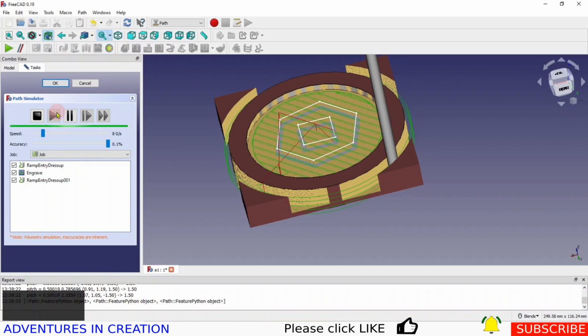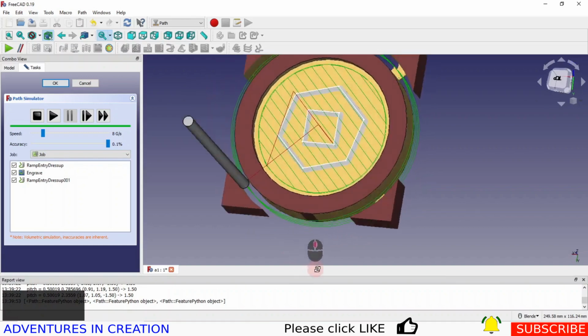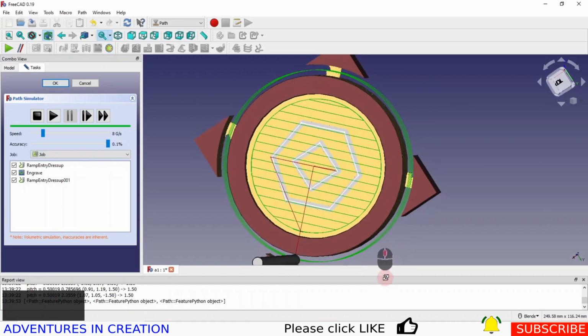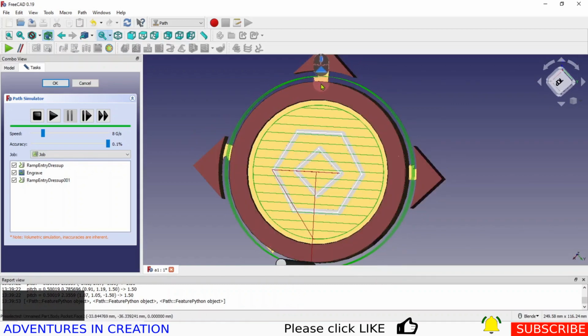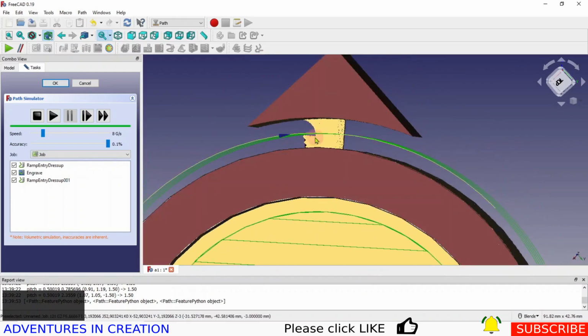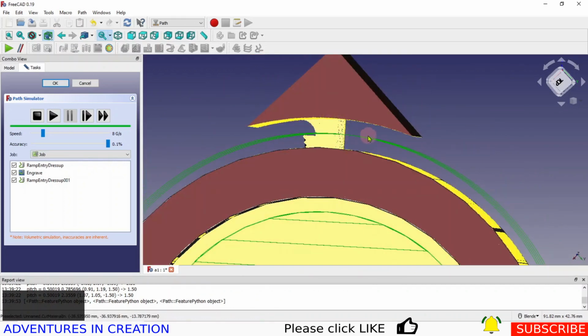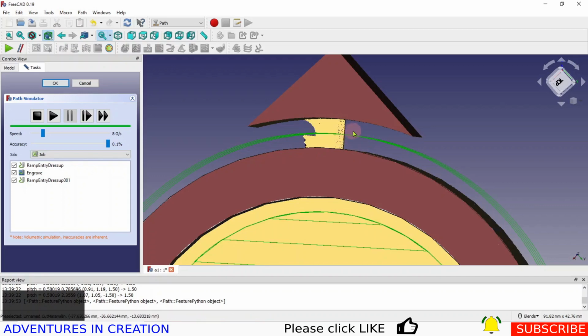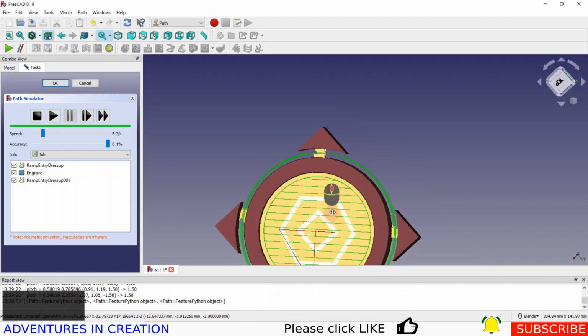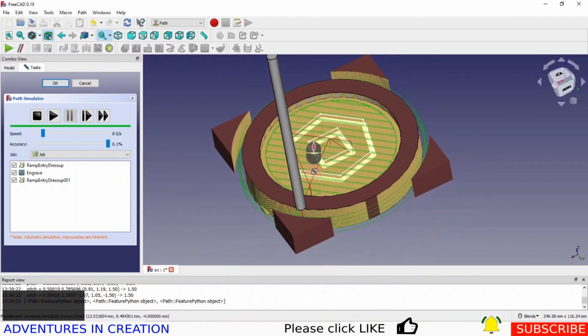Basically what it does, it lifts up the cutter as it's going around. And I think we're close to being done there. And there are the tags. You can see them in there. So the way it actually cuts them out is it'll cut to here, it'll raise up, come over here, and it'll cut out. So you'll have a radius of the tool on both sides, so it's not exactly accurate the way that that's displaying it.